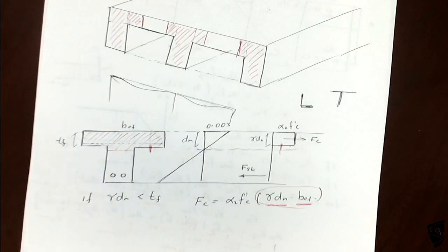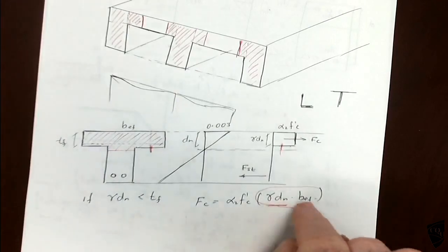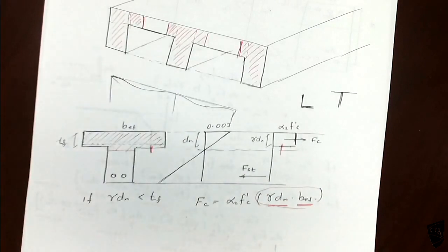You might have some variation in the area of concrete. So this is the normal case when you have slab and beams cast together. But if the slab and beams are separated, something like a precast beam or precast slab, then a rectangular beam should be enough. Is it clear?